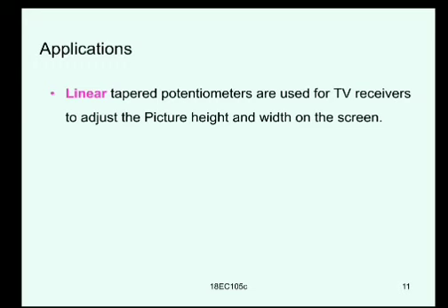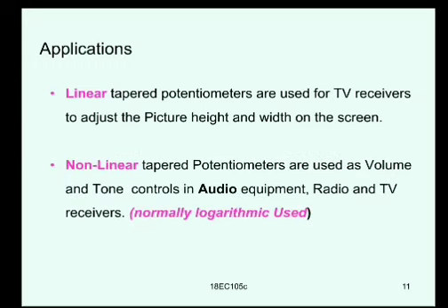So here the nonlinear tapered potentiometers are used as volume and the tone controls in audio equipment and the radio and TV receivers. Here the point to be noted is that the nonlinear method is mostly implemented in a logarithmic way. So the volume control and tone control are logarithmically variable parts.